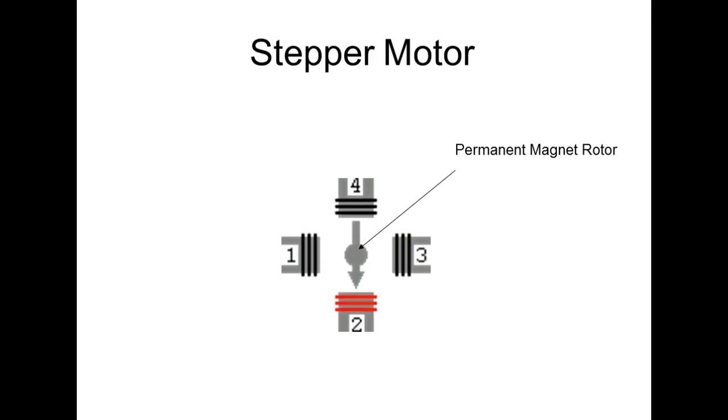In certain motors, you can do what they call half steps, if you control it right. So if you got 720 degrees, if you half step it, then you'd have twice that many. What they do is energize two coils. They'll energize this one, and it'll move to here. Then they'll leave this one energized and energize this one, and it'll move directly into the center. Then you turn this off and leave this energized, and it would move to 3. That's called half stepping the motor. So basically, if you half step the motor, you get twice as many steps per rotation. These things are neat.